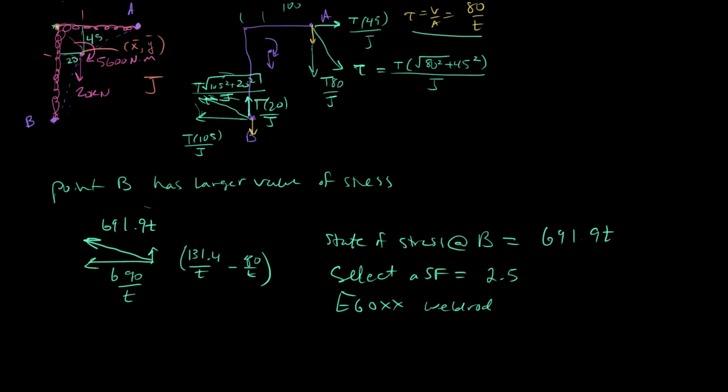And that is the tensile strength, which is actually the ultimate tensile strength. So we have to take the yield stress to define failure. So I think tensile strength is a little bit over 400 megapascals.